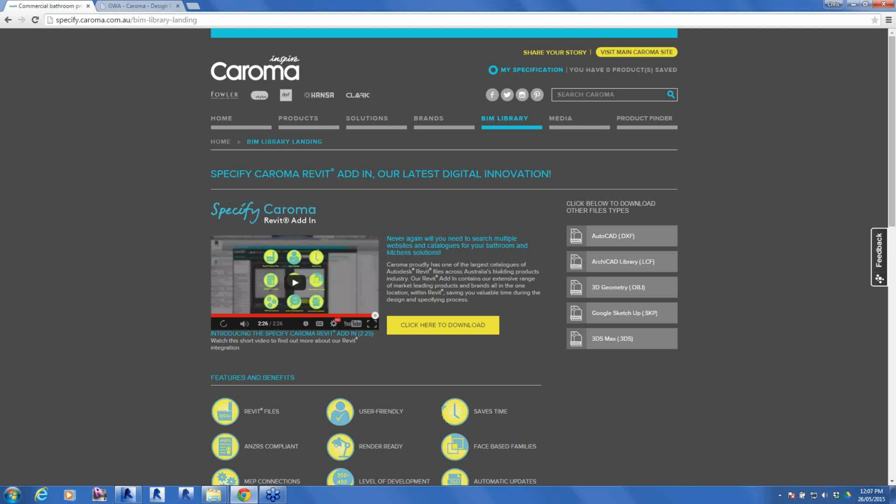Just reiterating some of what you saw in the video, there's over 1,000 products catered for in the Revit Caroma content library. It includes sanitary ware, toilets, urinals, bidets, basins, baths, shower bases, sinks, kitchen sinks and lab sinks, various tapware, and accessories like robe hooks, shelves, towel rails, towel rings, and many others. Generally, the functionality is face-based families with automatic openings and cutouts where applicable, default mounting height, clear plan and side and front elevations, render ready with MEP connectors.